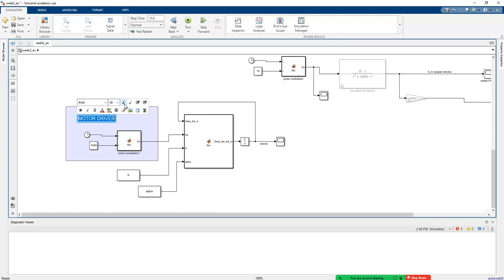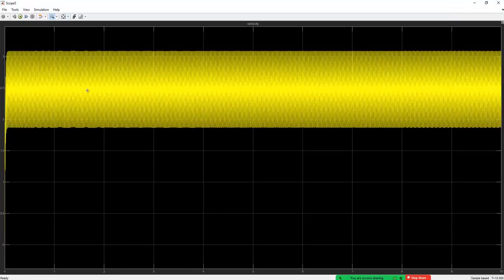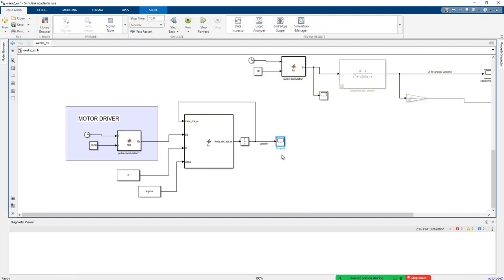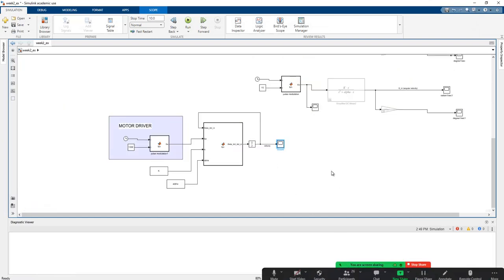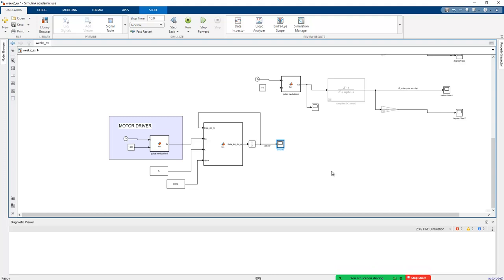Okay, and so this motor driver is used with some basic frequency with 1000 Hertz. Okay, and so if we had this Hertz, and then we can select or we can drive the specific points of this motor velocity. Okay, this is how we can achieve to our controller system in order to what? In order to represent in the domain of the PWM signals. Okay, because in the microcontroller we just only use this timer in terms of the frequency of this timer and the duty cycle of this timer.